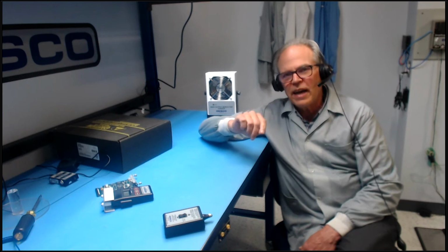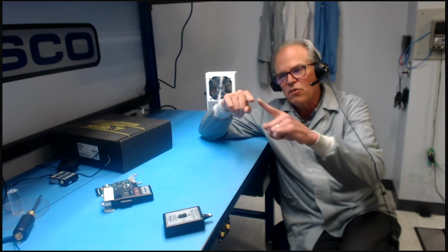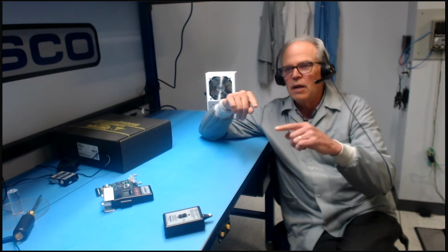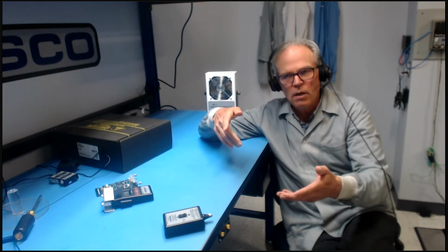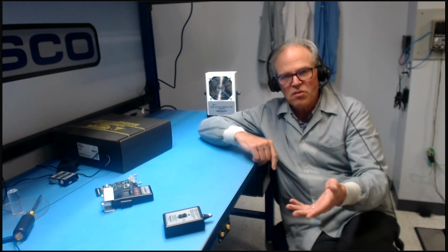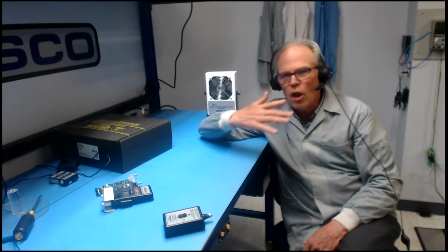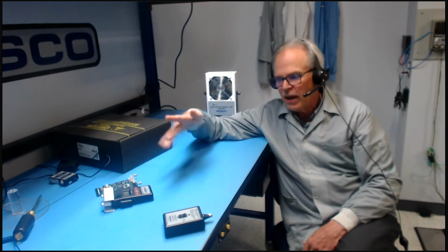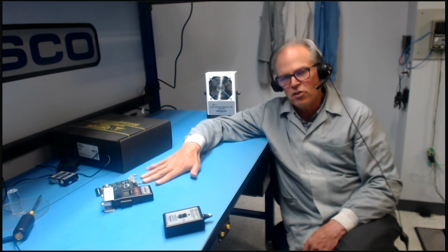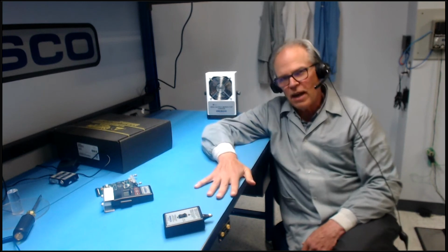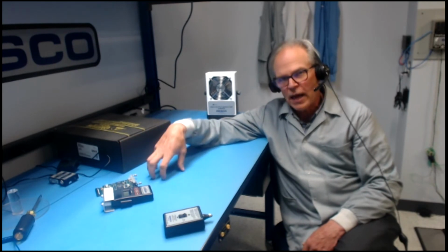Generally, an ionizer needs maintenance when the emitter points that the ions are produced from get dirty. They get rounded, kind of like a spark plug in a car. If a spark plug gets all dirty and gummed up, it's not going to work as well, and it will produce fewer ions. There's no law or standard saying you have to test. It would be a good idea when you buy an ionizer to test it when you first get it, and then maybe after a month, and then after a second month, to see the difference in performance and give you a baseline.